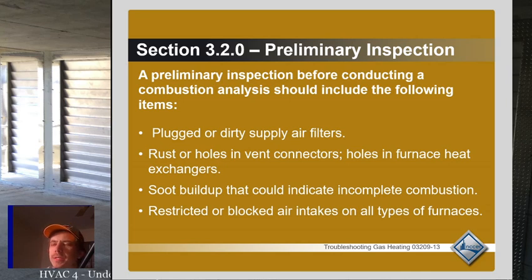The other thing to look for is if there are combustion air openings in the room. So say the room is too small for the combustion equipment, or you get combustion air from the outside, or you get combustion air from other rooms in the space. You want to be checking to make sure that those aren't blocked off or anything, and that they're sized large enough. If you know how to size them, you can double check the sizing and make sure they were sized properly, because I've seen those undersized a lot of times, especially when people start adding equipment in rooms and things like that. So that's something else to look for.